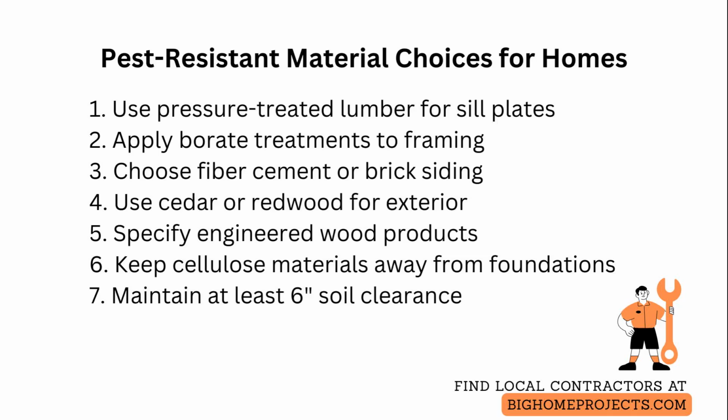Design for good drainage by grading away from the foundation, installing gutters and downspouts that discharge water well off the building, and providing continuous exterior water-resistant barriers so pests are not attracted by persistent damp conditions. During specification, include detailed installation notes for contractors about ventilation, flashing, and gap tolerances so fieldwork preserves the intended pest resistance of the chosen materials.